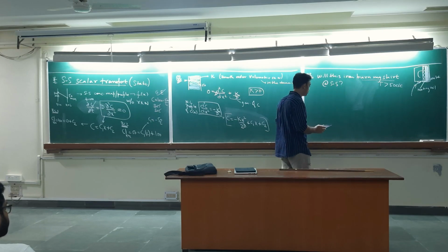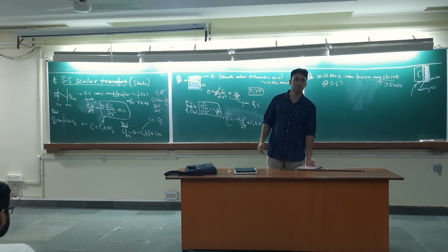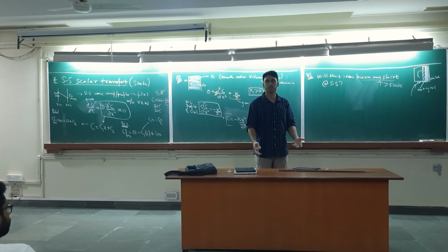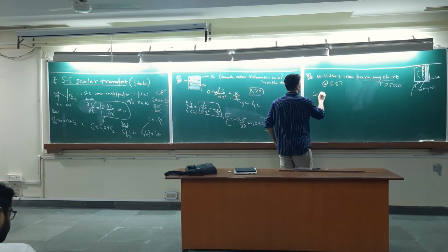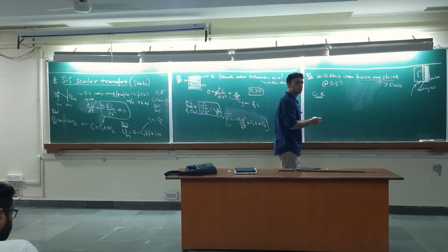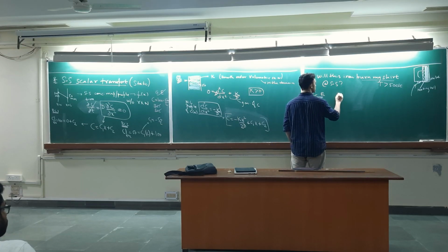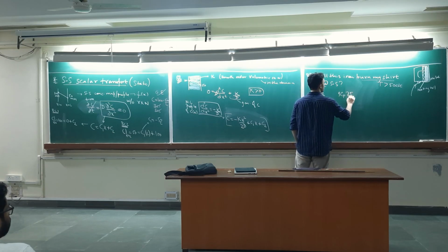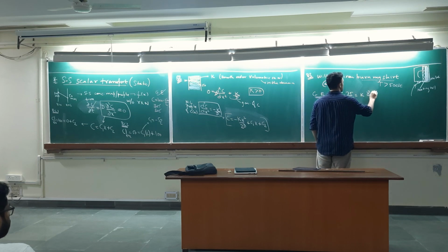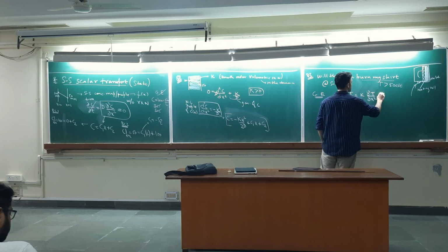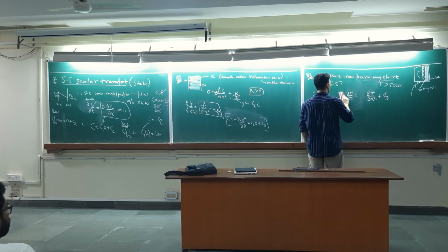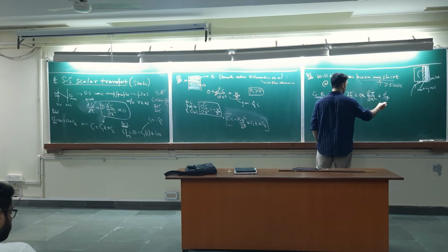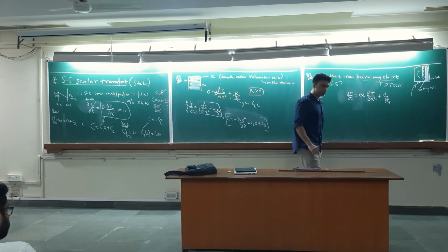Now, what all information will you need to model this system? First thing, what will you do? What did we do here? Governing equation. Very good. What is the equation governing this? Let's write down the entire one and then take out the terms. So you have rho Cp dou T by dou t is equal to K dou square T by dou x square, this is one dimensional, plus E gen dot. Now I'll take rho Cp on the other side, make this thermal diffusivity.